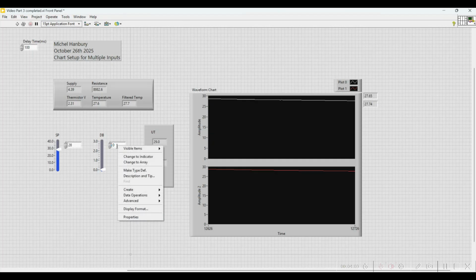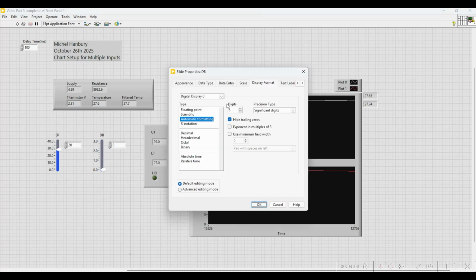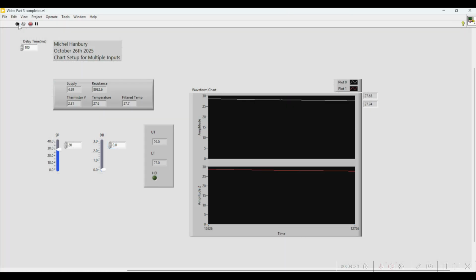And I'm going to click on this box and go to properties and look at something. Well, this is what we didn't get to change before. Let's see if we can do that now. So one digit of precision for temperature, these digits of precision. Select OK. I'm going to try running this now. And yeah, I'm able to go up and down, but notice I'm going above 7 and that I can go below 3. So let's change things so that doesn't happen.